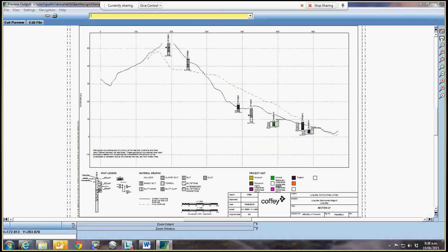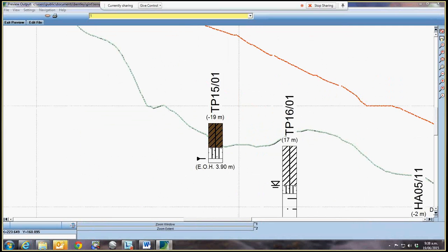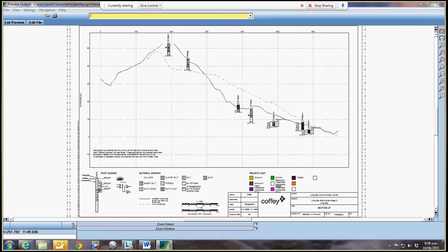So I think the green one and the black one are overlapping. But basically it's telling me the contractor's going to chop down this hill and push some of the dirt out to probably build terrace lots or something. And then it looks like some of my trial pits are floating up in the air. It's just because they're offset up to 20 meters and the ground comes up a little bit as it goes away. And same thing here. So I would not adjust those in CAD. They're accurate. It's where they're supposed to be as long as your GPS points are good. So, yep, now I'm pretty happy with this.